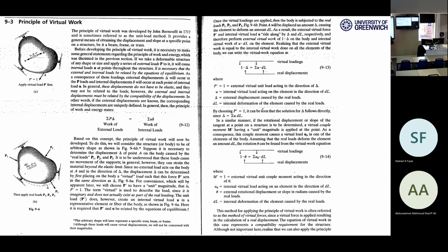And the previous approaches just take bending moment into consideration, right? All of these force methods are still somehow inferior to the deformation-based methods or stiffness-based methods, which is the next one. I showed you some of the steps in your coursework are about the direct stiffness method. The direct stiffness method, or matrix analysis, is based on deformation-based approaches.